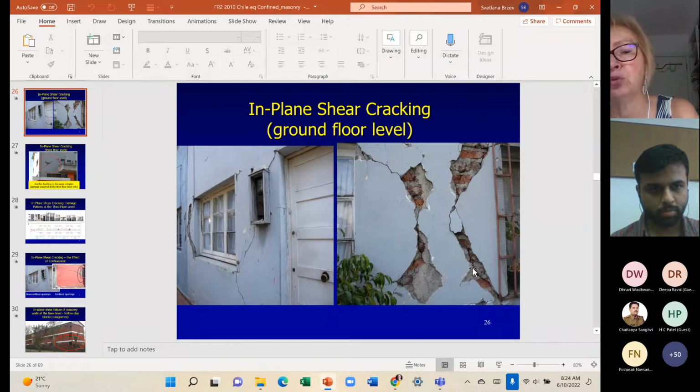So it would not need to be demolished or anything. It could be restored, because the technique is very effective, and it could be done double-sided, both exterior and interior. That would be the repair technique, and I would assume that's what they would do. Because of these cracks, they wouldn't demolish the whole building. Obviously, there is no justification for doing it.